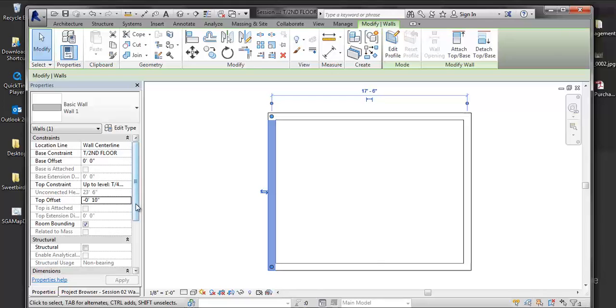So you said you would do that by aligning it to the Yep, just like we did with the electrical boxes on the house, yeah. And you would do that to the base of the wall and to the top of the wall? Not to the base. The base you would still constrain to the level. Yeah. It's going to always be defaulted to the constraint of the level.